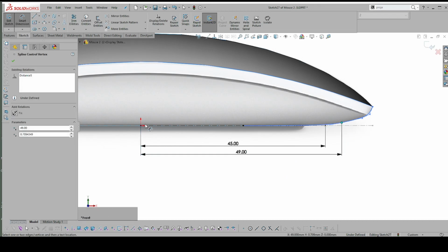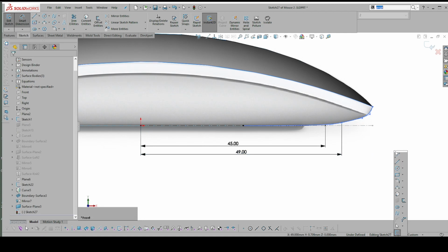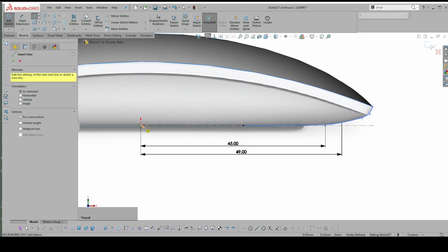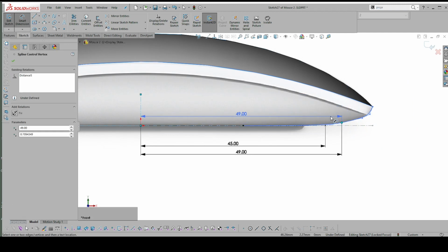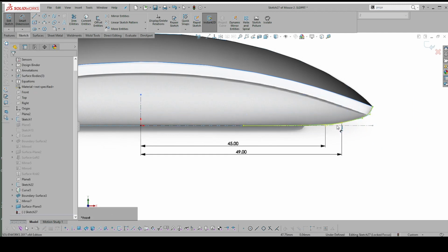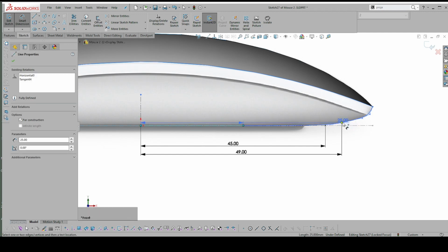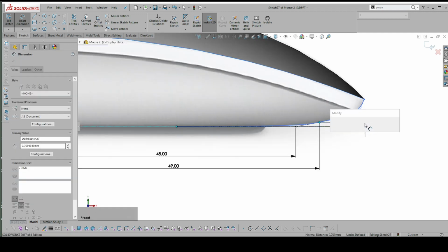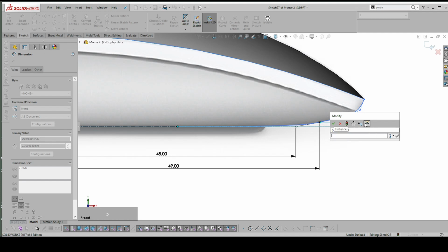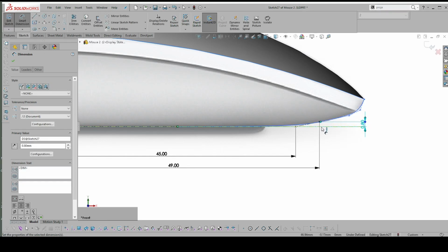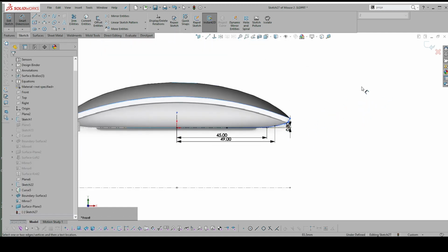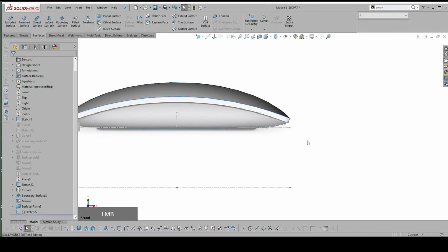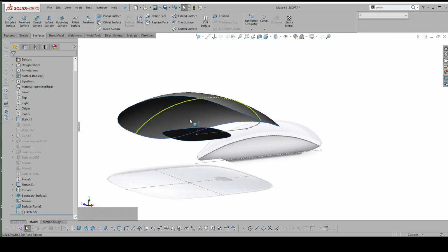And this will only go black. Obviously, I will need a vertical line here to dimension that one height-wise. No, would I? Yes. I would need that one there. Let's go like that. So I'm not going to do this in full, 0.8, just to show you that you can dimension this, and then when you fully dimension it, it'll turn black. And that's good enough. We only need one curve at the moment, one spline, because we're only going to do a quarter of this item.